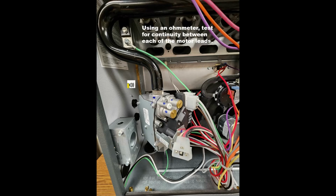And we use an ohm meter to test for continuity between each of the motor leads. We see here, and all three of them, we have continuity. And if we didn't have the continuity between the three, you'd change the motor.